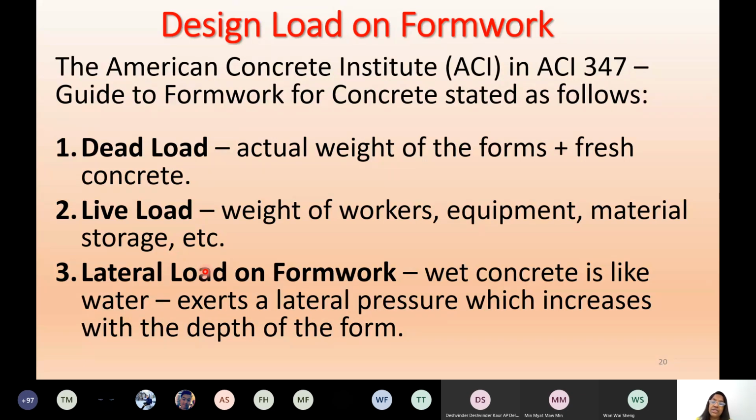It will exert a side pressure onto the formwork, which may affect the shape or the dimension of the formwork. So care should be taken that the built-up pressure due to water on the sides is avoided, maybe by controlling the time or the proportion of the concrete. This type of loading is also inevitable, we cannot avoid it, because it's a slurry form. Until it gets hardened, there will be a chance of this loading.